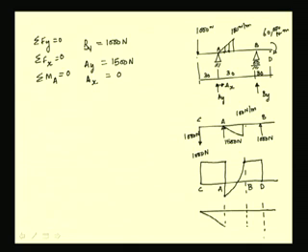At D we have a negative moment, and the area under the curve constantly increases, and between this portion AB it has to be one order higher. So it becomes a cubic curve. So in this fashion we can construct the shear force and bending moment diagrams using the differential relations.